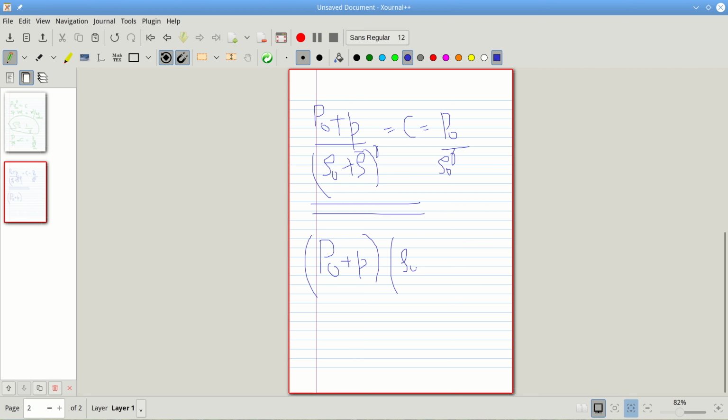So I can pull out rho naught to the power of gamma, and I have rho bar by rho naught, right? Remember that rho bar is very small compared to rho naught, so I can do a binomial expansion. So it is rho naught power gamma, and then multiplied by the first order expansion, which will be 1 minus gamma rho bar by rho naught, right? So this is coming from that binomial expansion.